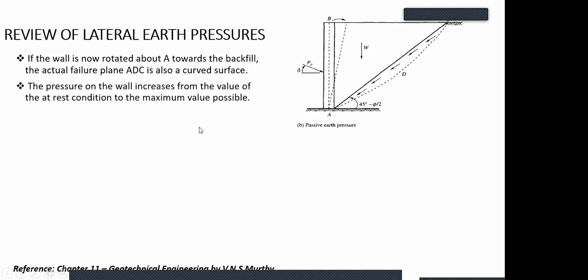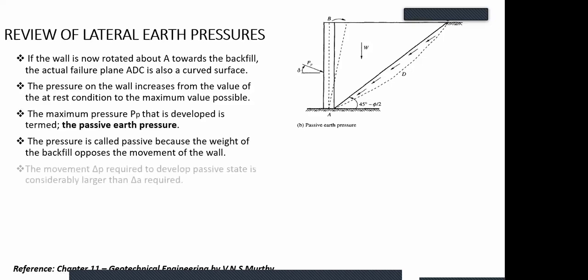And for your design of retaining wall, we don't really use passive earth pressure. We use active earth pressure. But for sheet pile, we use both of them, both active and passive. So that's basically all I think I've said.